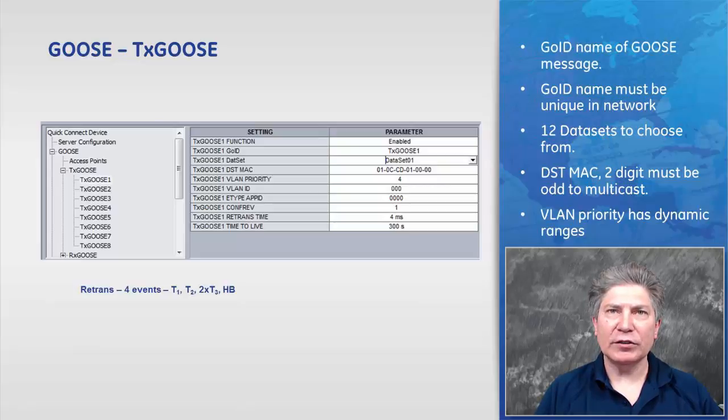One of the choices is 7-5. So what that means is the first event goes out with a priority of 7. The second would have a priority of 6. The next would be 5. Then the next one would be 5, and then so on. So the standard indicates the priority for Goose messages should be in a range of 4 to 7. I'll skip the VLAN portion.